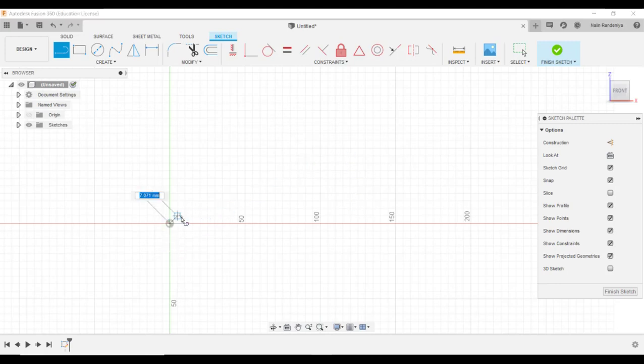I click on that. How it works is click to click, you are drawing a line. And I have turned on the chain line option. That means I can go click, click, click, click, click, and we have a chain of lines. But before I go into that, notice there are some values changing dynamically. The first thing is the length, you can see, and the angle.